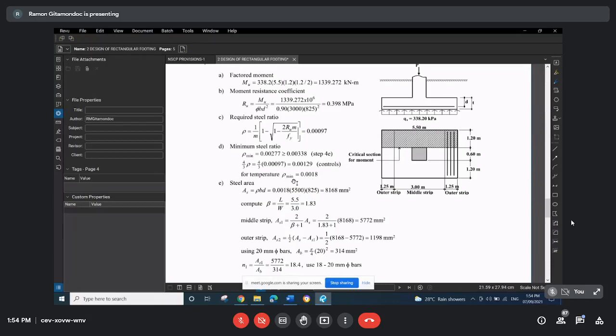Now actually, this is the amount of steel reinforcement we need to supply to control thermal and shrinkage cracks. As the concrete dries up, it will lose moisture, then tensile stresses will develop in the concrete, especially if that shrinkage is not allowed to occur freely.